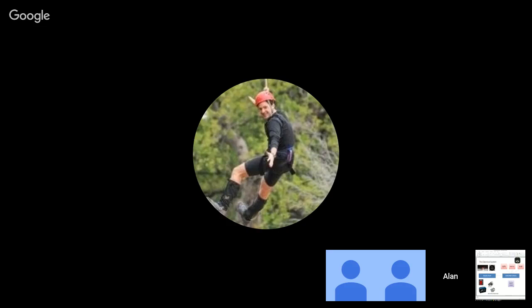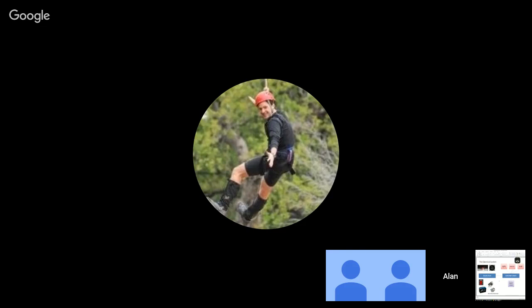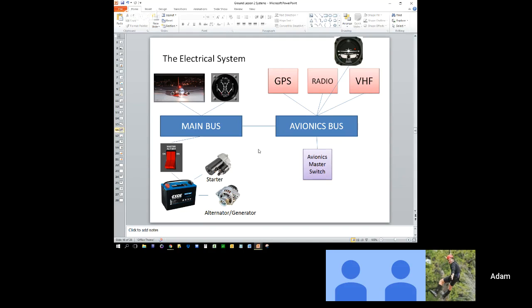The fuel pump. Oh, that's a good answer. Yeah, the fuel pump is missing from here. Now, you've got a fuel gauge. I think that's what you meant by that. Well, you're right, I mean the fuel pump. A non-gravity fed fuel system will have an engine-driven fuel pump, which is driven from the engine, and it will have a backup fuel pump, which is electrically driven. So yes, fuel pump is a good answer. I was looking for a particular answer though.